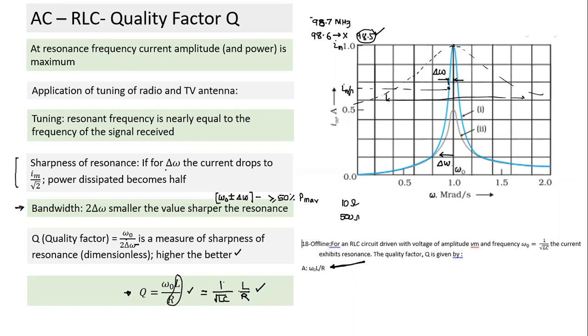And the previous example, if you go through, I gave previous 2 examples. What I gave was to help you understand. In one case, see, when L was 10, when omega was halved, the current became less than 1%. Whereas in the other case, the change was only 8%. When R was high, that's what this formula also indicates. If R is low resistance, quality factor is high, it means the drop is very steep. Sensitivity is high. And that's what the example also indicated.